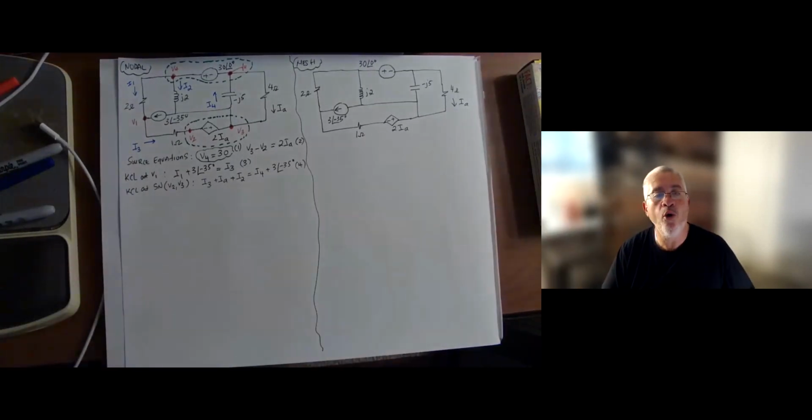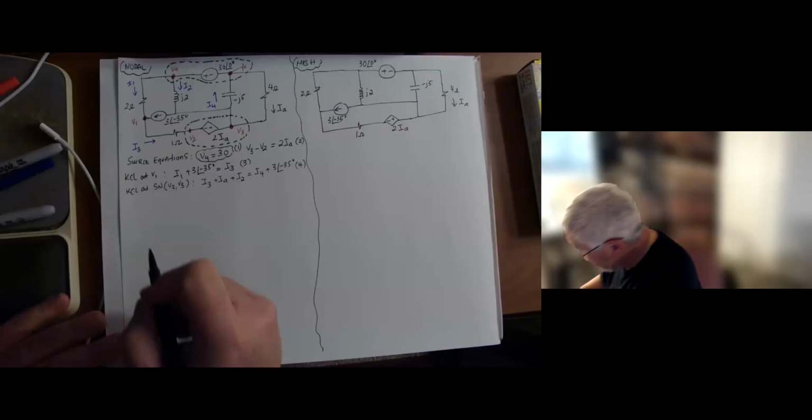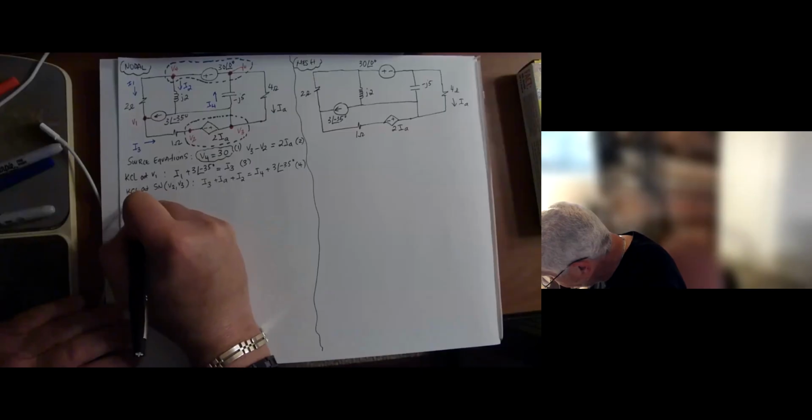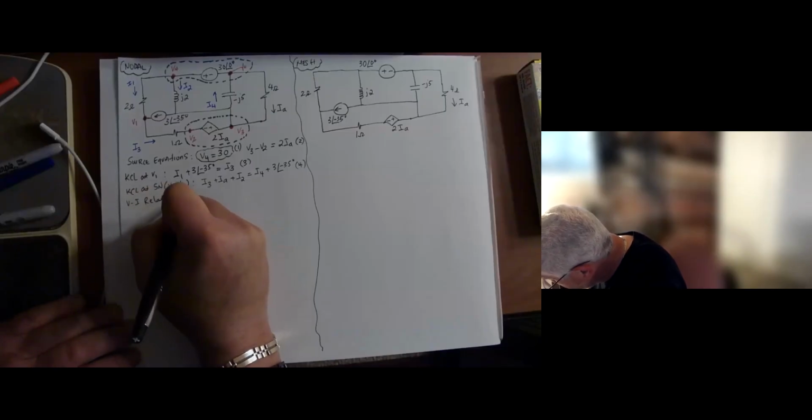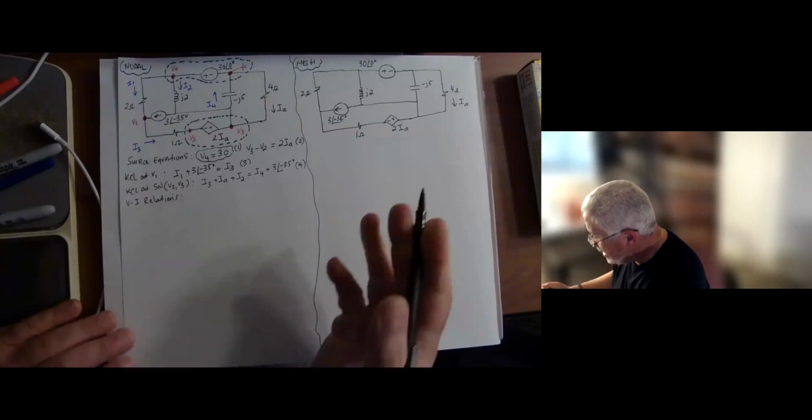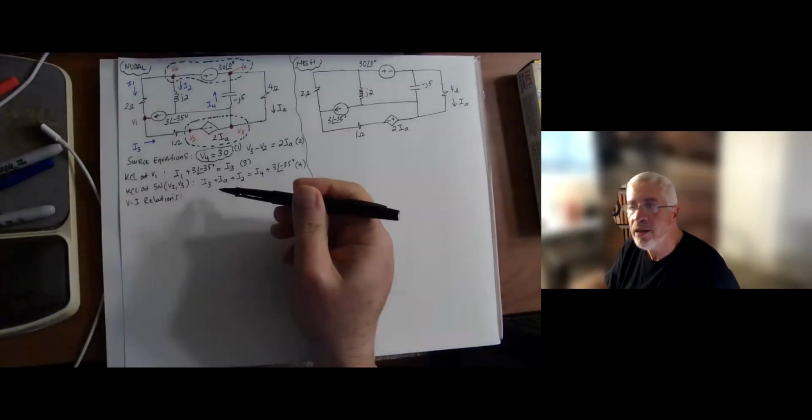So these are my 4 basic equations for the node voltages that I need to calculate. Two come from the sources, 1 source equation per voltage source. And then KCL at the regular node V1 and KCL at the supernode that doesn't have the reference node. Okay. And now I'm going to write the voltage-current relations. That essentially allows me to go from currents to node voltages.